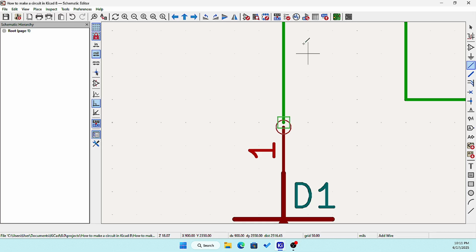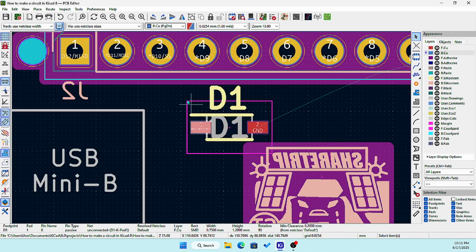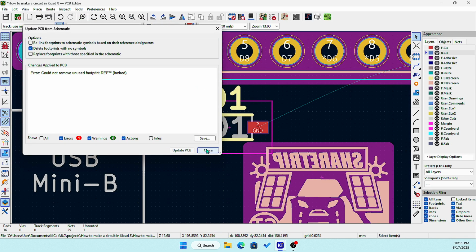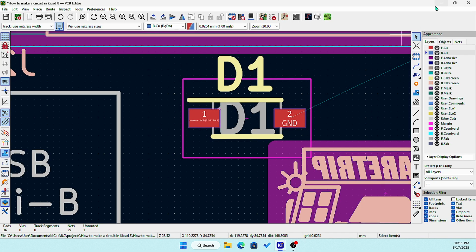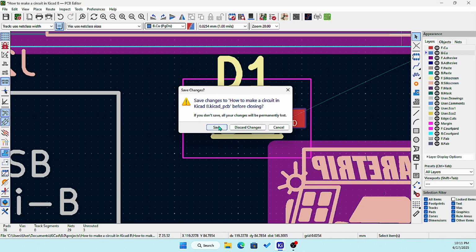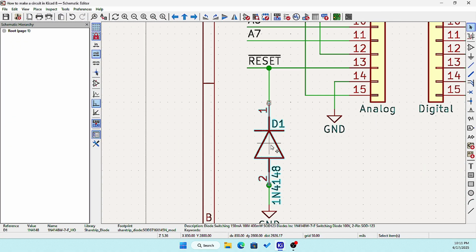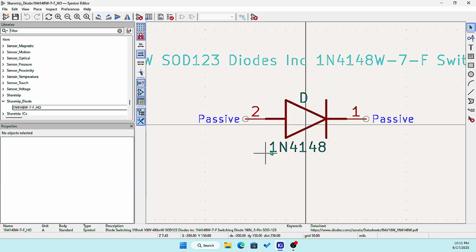So this is problems that you could have. Okay, that's not right, but you gotta understand why it's happening. What's the problem? You just don't throw it there and say I'm done. No, find out why. Do I go crazy about it? No, I just go here, go to properties, go to edit symbol library. There's something wrong with my symbol.